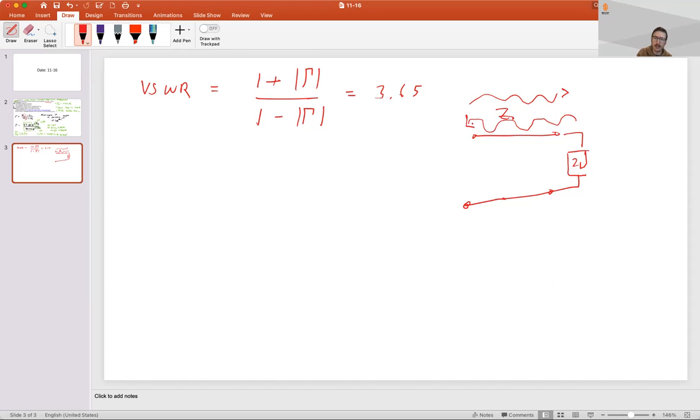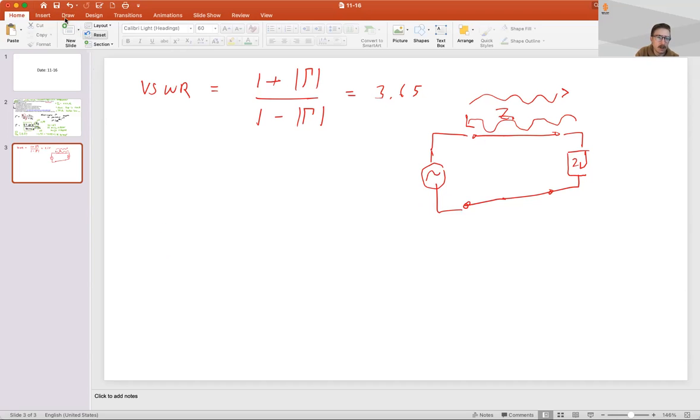because the wave that's being reflected back, eventually on this side, you're going to have some other electronic equipment back here, probably some kind of a voltage generator or something. And if it's not protected well, this wave that's coming back can damage any electronics over here. So this is a somewhat high voltage standing wave ratio. Okay.